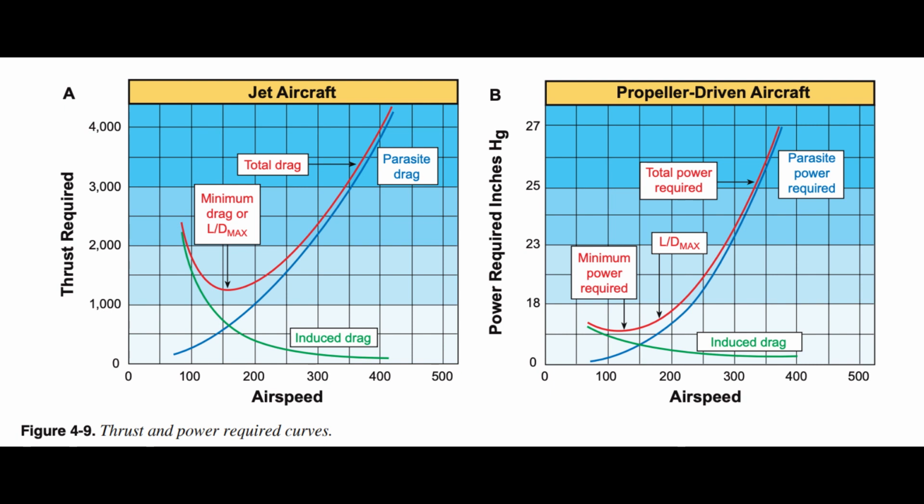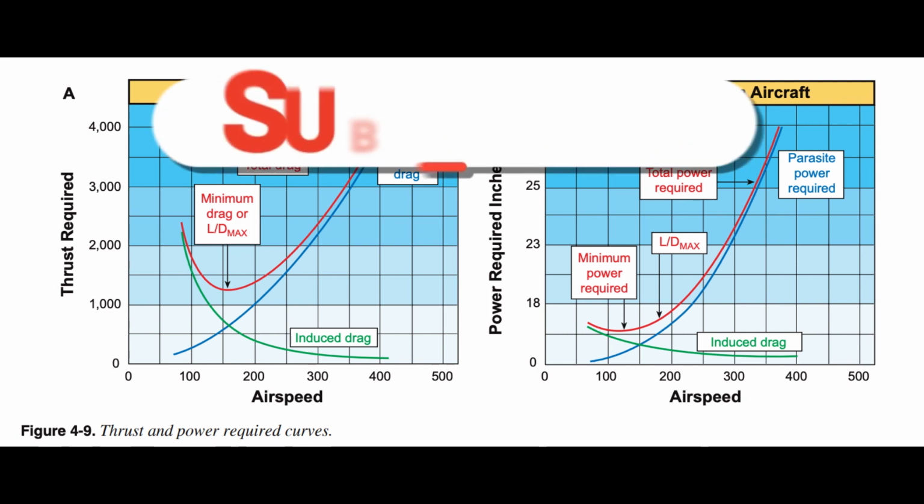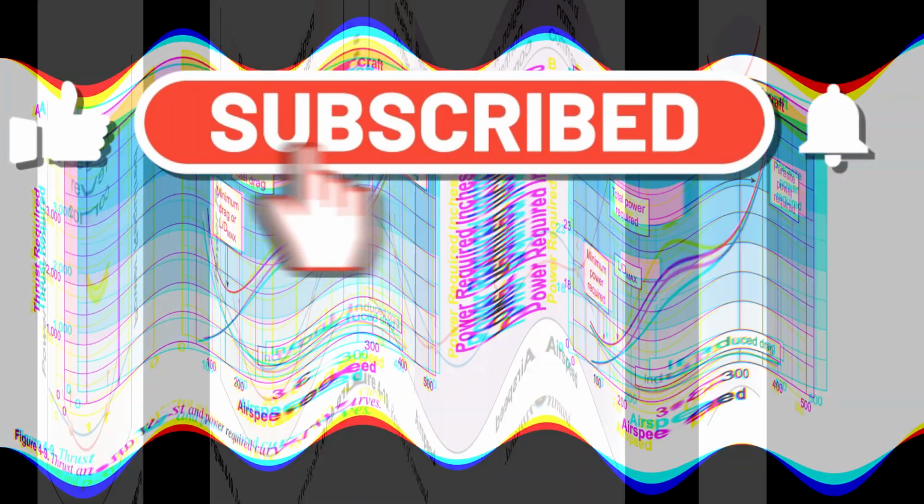The propellers used on most reciprocating engines achieve peak propeller efficiencies in the range of 80 to 88%. As airspeed increases, the propeller efficiency increases until it reaches its maximum. Any airspeed above this maximum point causes a reduction in propeller efficiency. An engine that produces 160 horsepower will have only about 80% of that power converted into available horsepower, approximately 128 horsepower. The remainder is lost energy. This is the reason the thrust and power available curves change with speed.